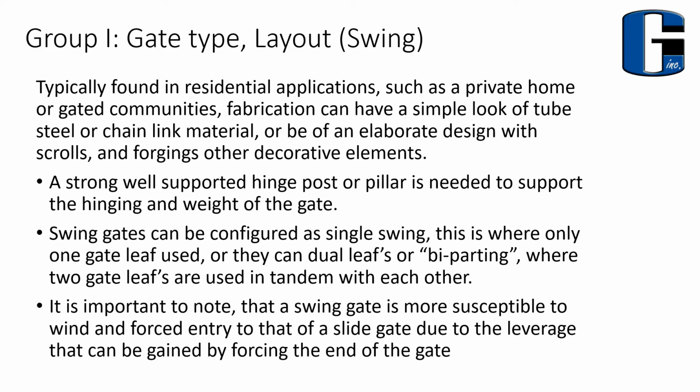Swing gates can be configured as single swing. This is where there's only one gate leaf or gate panel used, or they can be dual leaves or 2 gate panels, which we refer to as biparting, where both gate leaves are moving and opening and closing in tandem.